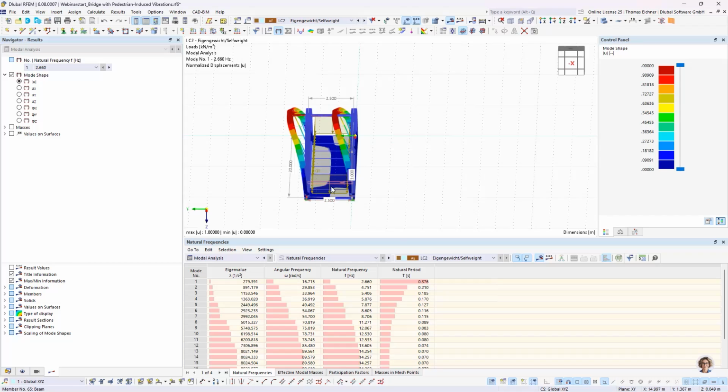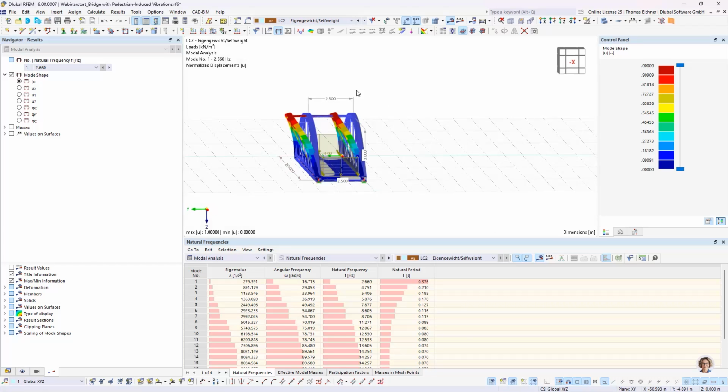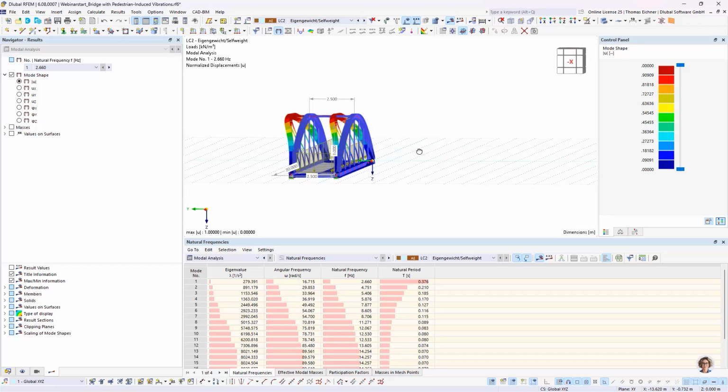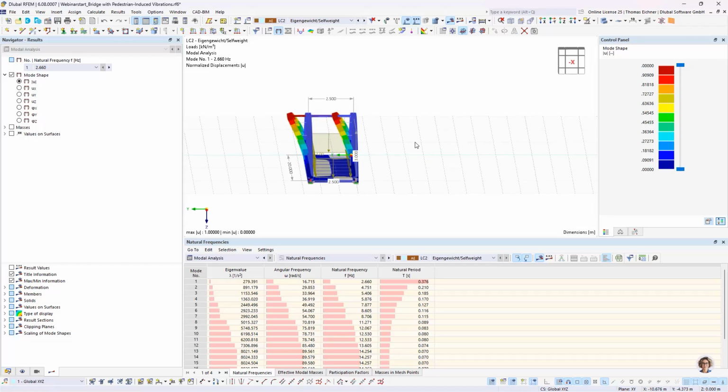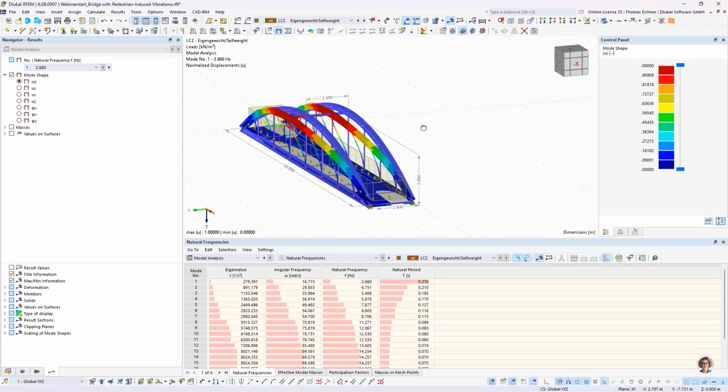That means we have a vertical loading here, 1 time for the right foot, 1 time for the left foot, and so on. That also means that, for example, this eigenform does not move in any way in the direction of our loading. So it won't really have an impact on our solution here. That means that eigenform is just not important for us.